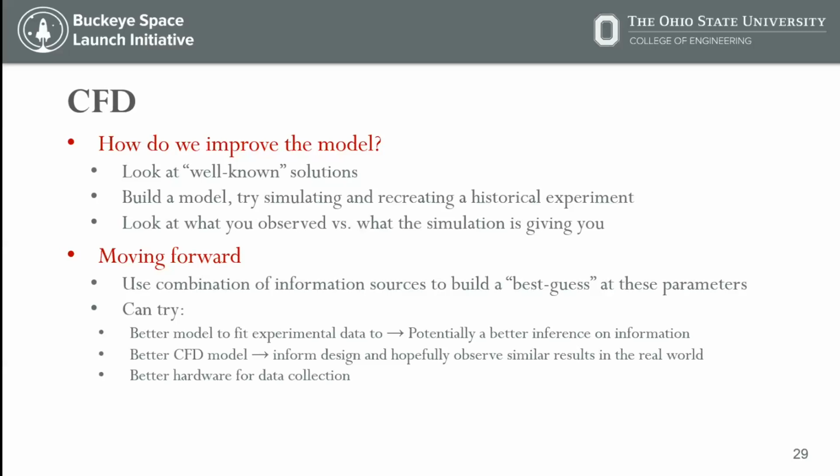So maybe for a baseline pressure and acceleration, it is probably okay. But if your rocket's not as stable as you'd like it to be, and it's turning over and going 60 degrees into the horizon like it did last year, then you probably want to know the orientation of your rocket and maybe try to guess at what your velocity vector is, instead of treating it as a scalar quantity, a vectorized quantity. Is that a 3-axis accelerometer, or is it vertical? It just depends again on the hardware that you're using.